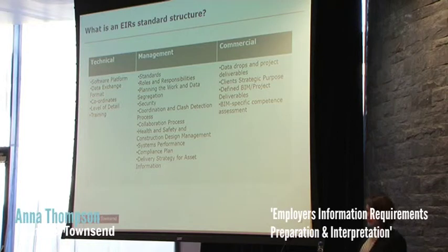If we look at commercial, it's looking at that competency assessment. Does everybody have the capability to actually work in this BIM environment and achieve the outcomes that we're looking for? What data drops? At what point are we going to take data out of the model, and what data are we looking for? What are the project deliverables? So this is what the content of an EIR should look like. So it's not a case of just saying, I want BIM.